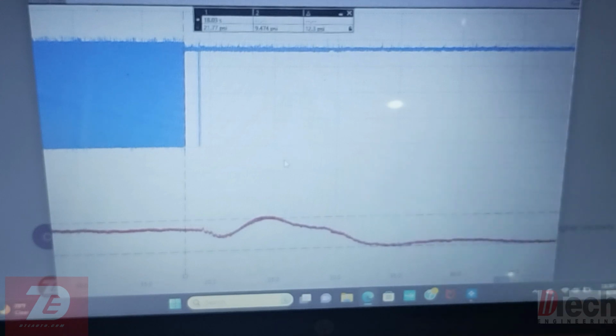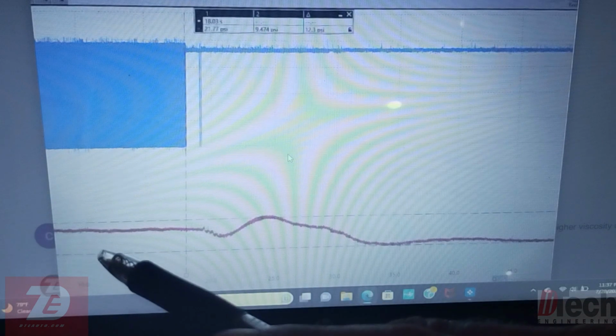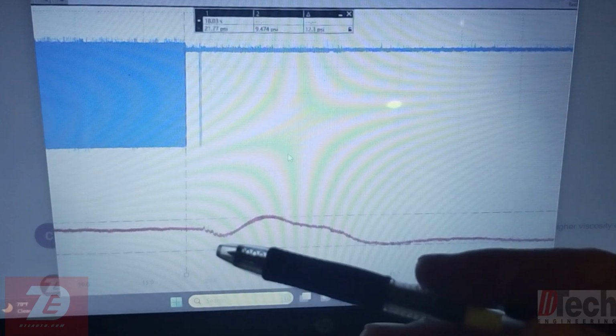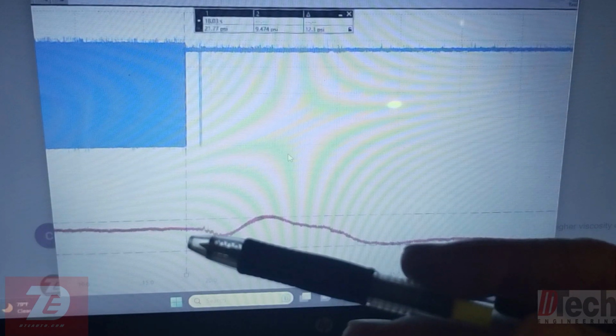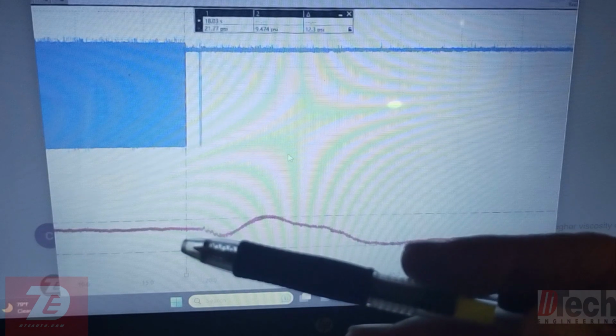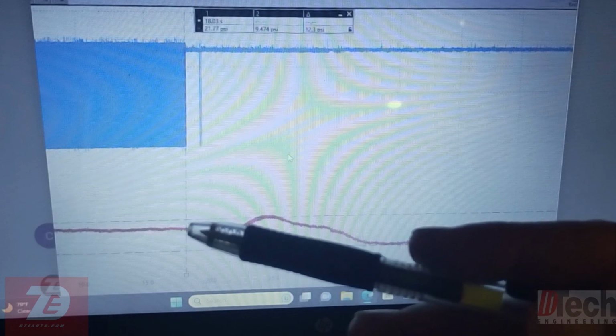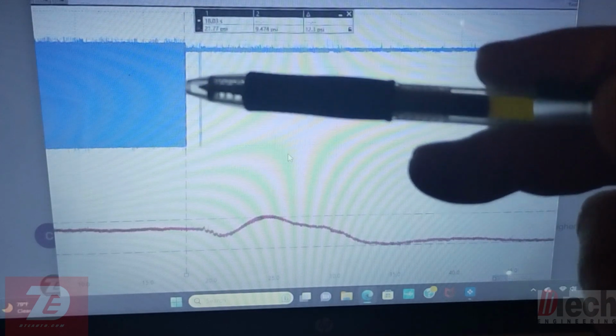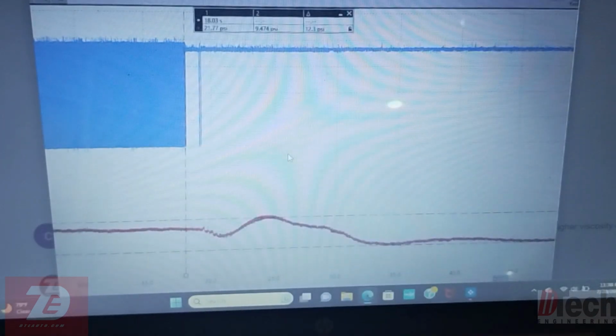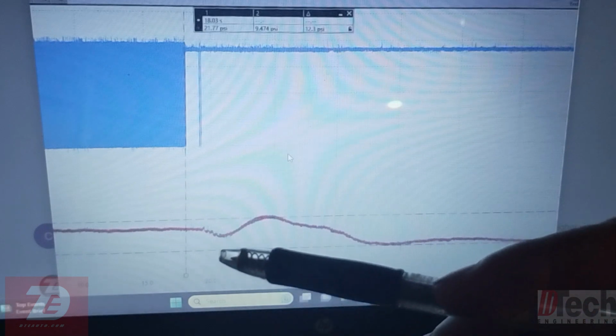So what is going on here is the oil pressure gets to such a low point, even though it's being controlled, that the DME is not happy and turns into almost a fail-safe mode and shuts off control and command of the valve, which then mechanically should shoot up the pressure.